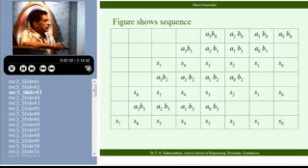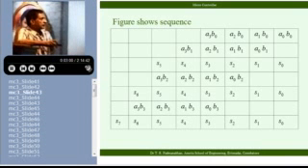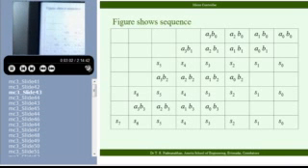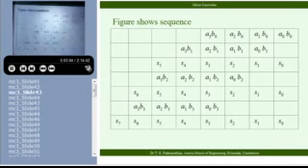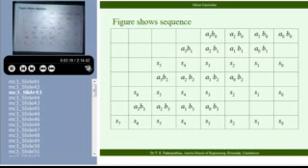Now, since it is multiplication with base 2, you don't have to do multiplication at all. See here, I have shown it as a table. A0, A1, A2, A3, that's the multiplicand. I multiplied by the least significant bit of the multiplier, B0. Next with B1, I have done the summation, that's the first partial sum. I align the next partial product, and form the next partial sum.